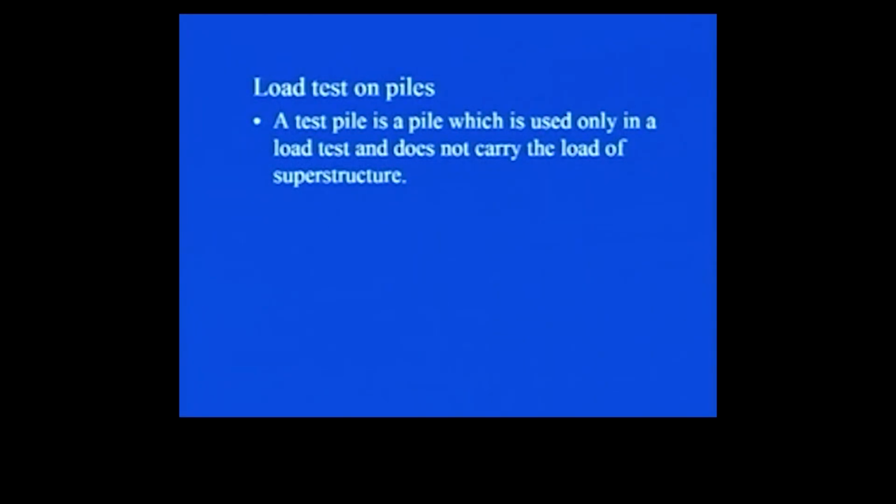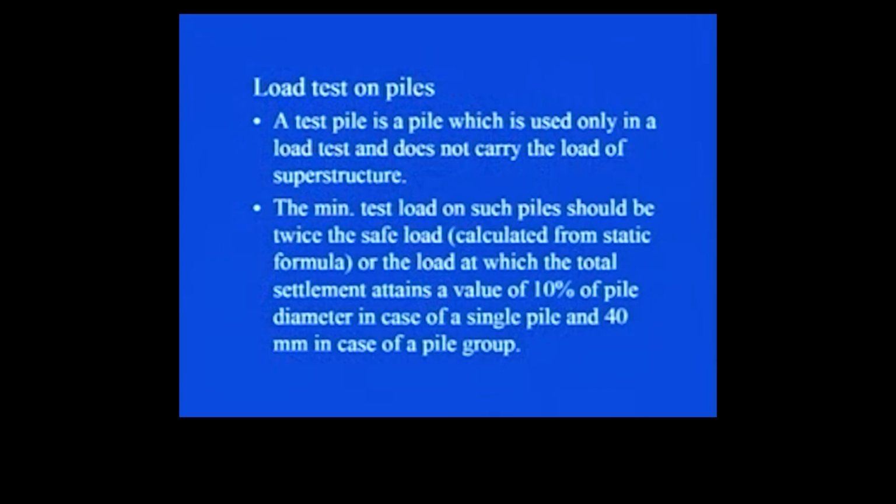Now, what is the test pile? The test pile is a pile which is used only in a load test and does not carry the load of the superstructure. It is constructed, installed just for the purpose of conducting the initial pile test. It does not carry any load from the superstructure. The minimum test load on such piles should be twice the safe load.